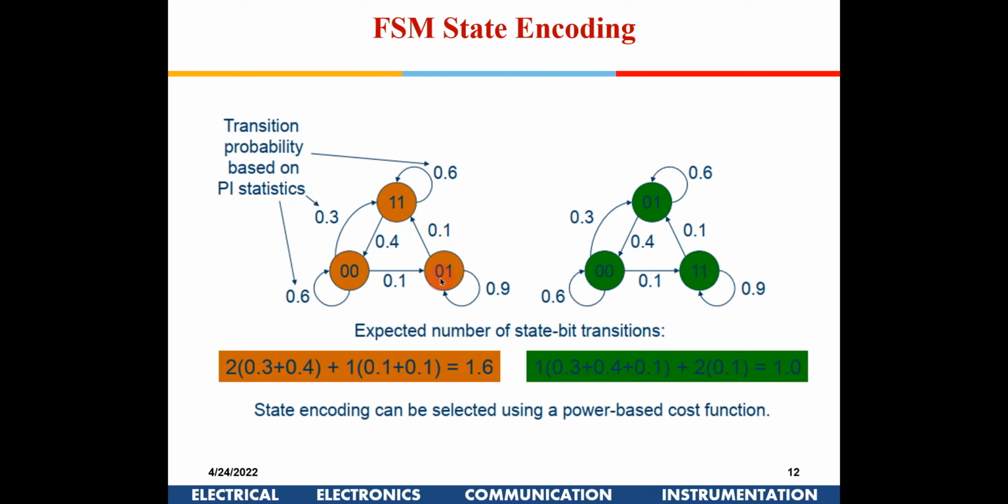That flexibility is available with the designer. This is a state transition diagram with 3 states, so I use 2 flip-flops. With 2 flip-flops I can have 4 states, so among the 4 I can use any 3. Normally we just put some arbitrary 3 values here and then go about designing the gates. Right now I am looking at saving power also.